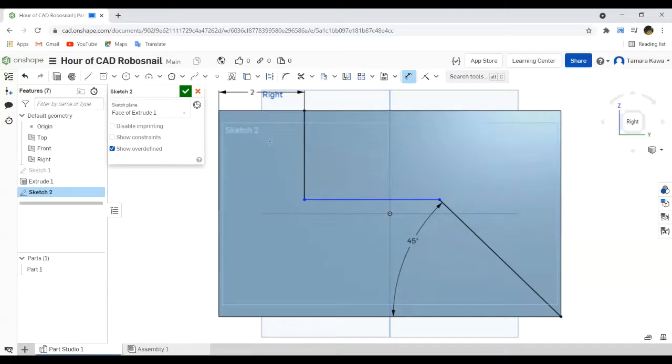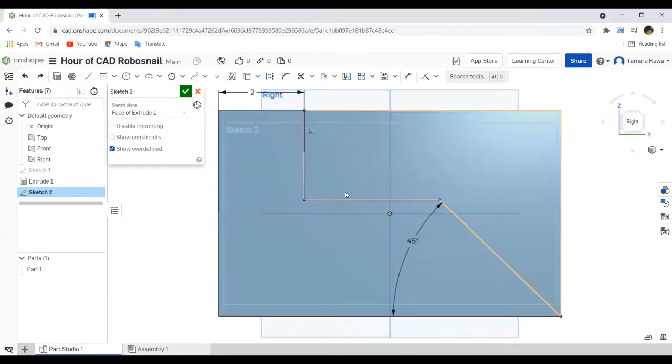All right. So let's see what happens if I try to define this. Do you think it's going to cause problems or no? Let's find out. It doesn't. And the reason for that is we have an angular measurement, but we don't know exactly how high that line is supposed to go. So let's call it 4 inches. And then you'll notice it dimensions everything else relative. Yes? Of course. All right. So this line, we're going to click on it with the dimensioning tool.